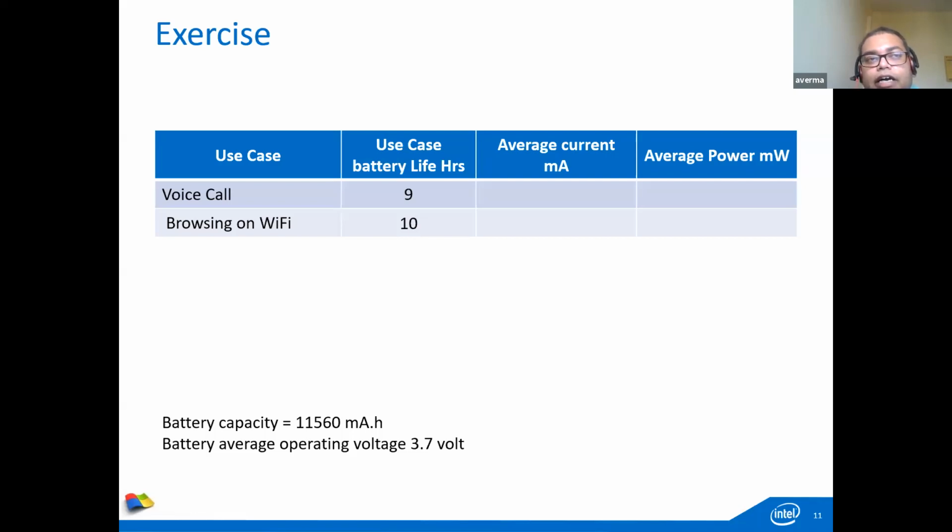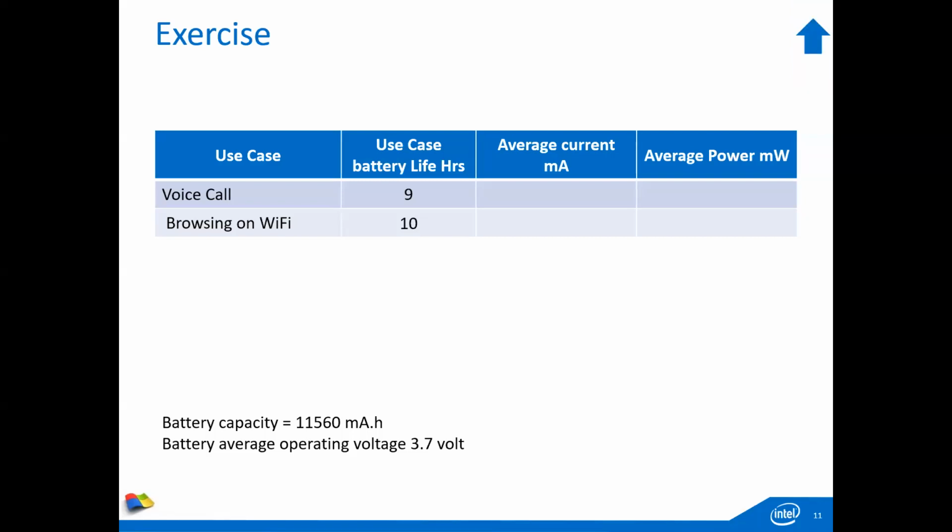You can get converter ICs which can convert from 12 volt to maybe 1.2 volt or 1.8 volt. What is the specification of your IC? What is the operating voltage that you need to find out? I don't know what exactly you are doing, but you should be aware of the required operating voltage for that IC, and it can be converted from 12 volt with converter ICs readily available in the market, maybe from TI or something else. Okay, thank you, sir.